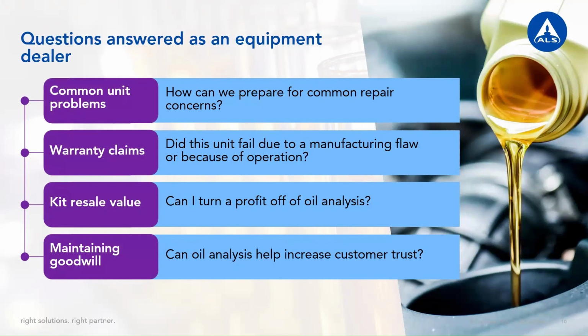Since we're discussing fleet managers getting the most out of their assets, equipment dealers can also utilize oil analysis to better market their products. When selling equipment, it's best to know your machines inside and out, especially if they are going to be coming in for repairs. Oil analysis can shed light on which problems each individual unit model shows. If you know for a fact that model alpha shows a tendency to have high axle wear when put under heavier than normal loads, your part choices can reflect the reality of its operation.